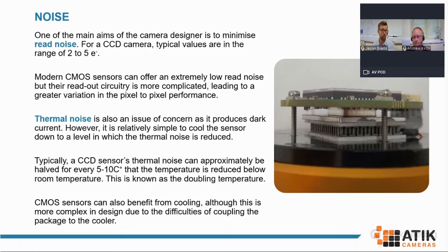Thermal noise however, is something that certainly impacts both sensor technologies and, as the name would indicate, refers to the process by which electrons are thermally excited and released from the silicon into the sensor. So the size and rate of it is related to their rate of release, hence it's measured in electrons per pixel per second. And it can be a very significant contributor to the signal to noise ratio, especially sort of at ambient temperatures. Cooling in that sense then becomes a very important aspect and capability of a camera, certainly for anything which isn't a very, very quick image.